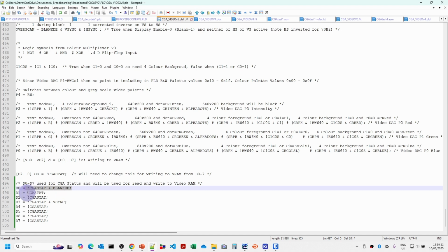These values, that's just going to be 0. This is set to 1. This one will be set to the vertical sync. Again, we can tell when the vertical sync interval is, so that the PC will only update the video RAM during the frame refresh period, and these other values are just going to default to 1.